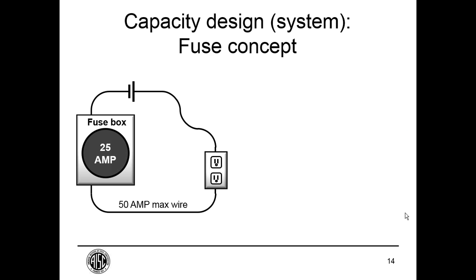And a good analogy for that is a circuit with a fuse, with the yielding elements being the fuse, which we would like to be weaker than the rest of the structure, which is the circuit, so that when we get failure, which we think we will in an earthquake, when we get yielding, we have yielding where we want it, and we protect the elements that would not have high ductility.